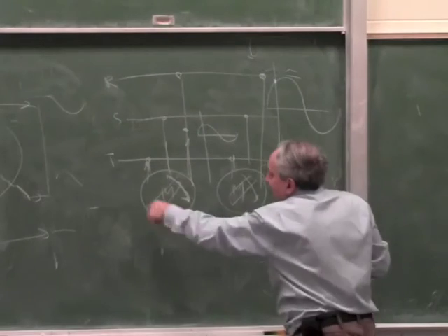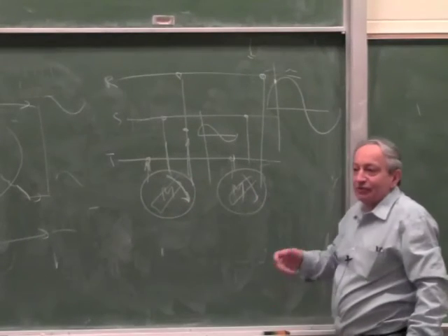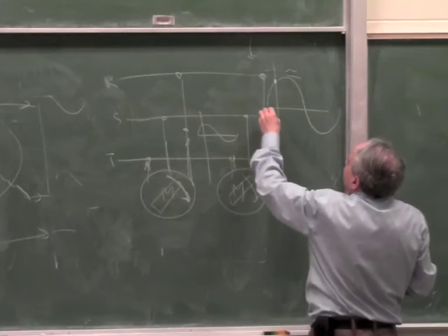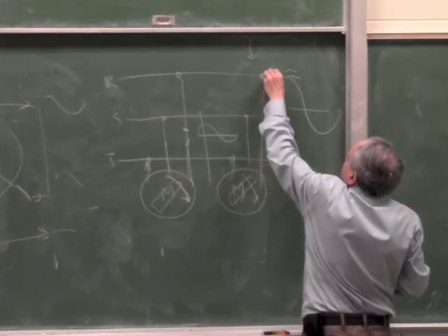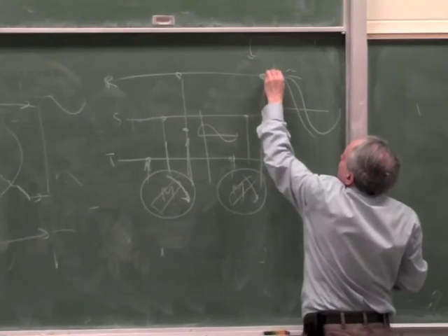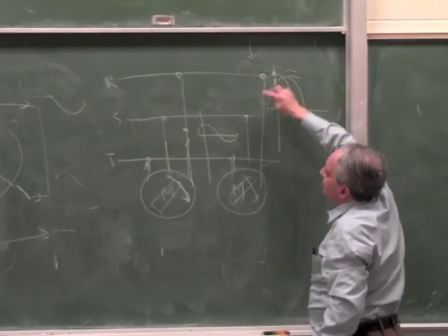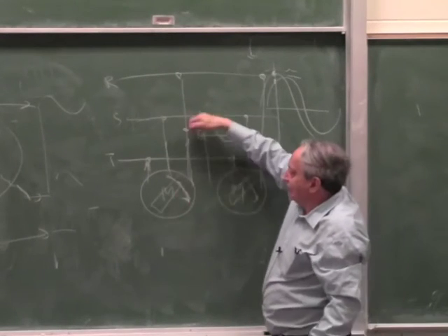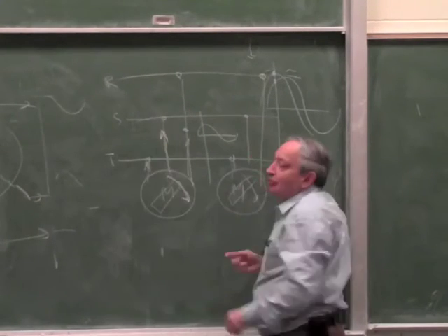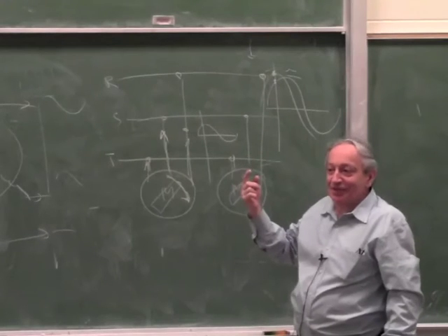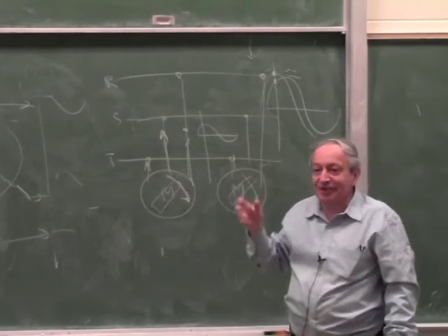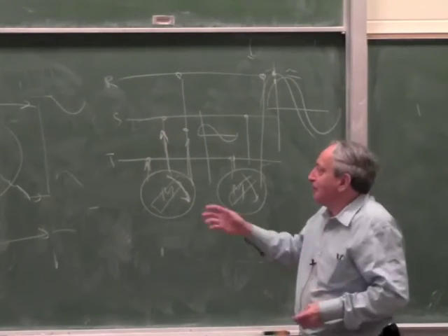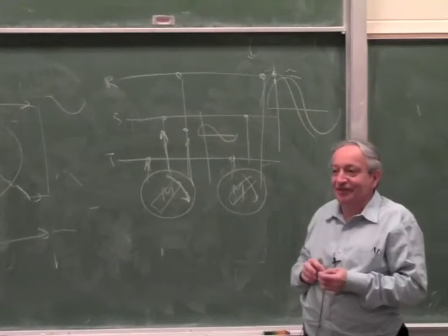Now let's say you're turning the motor faster than it wants to turn, so it generates its own phase, which is a bit ahead, like this. Its voltage is going to be higher than the voltage of the phase connected to it. So instead of current flowing into the motor, current will actually flow back. So when you have many motors connected to a grid, if you want to speed up the motor, you're actually feeding power back to the grid.